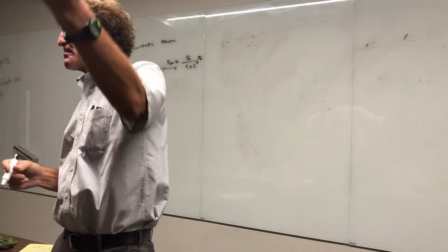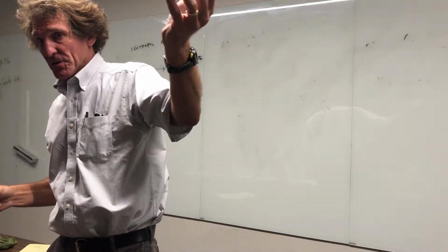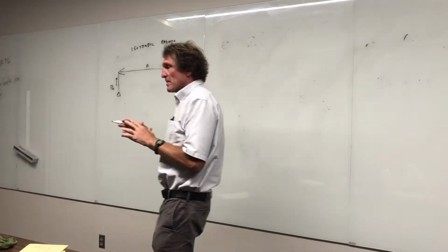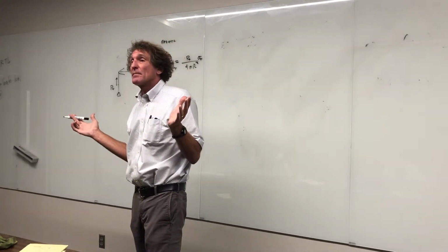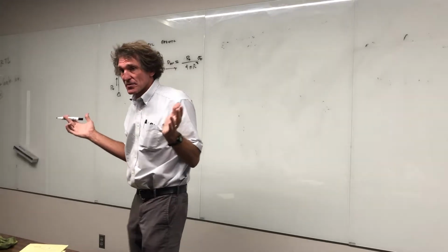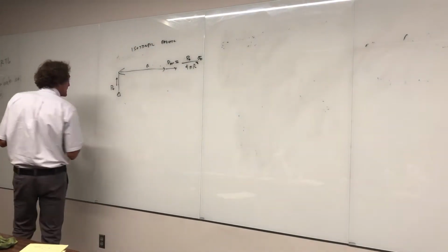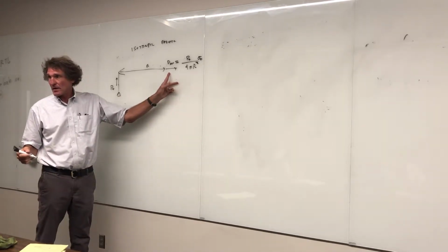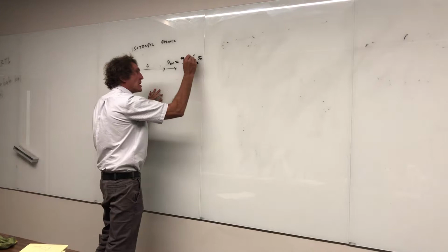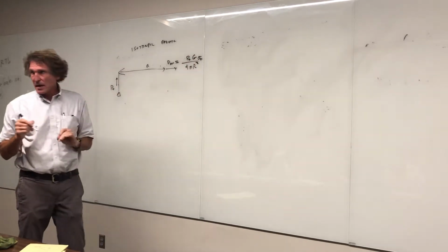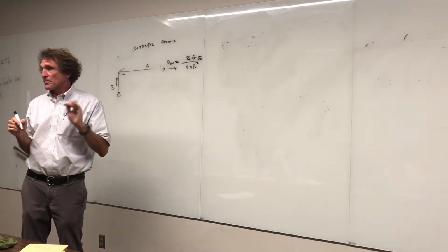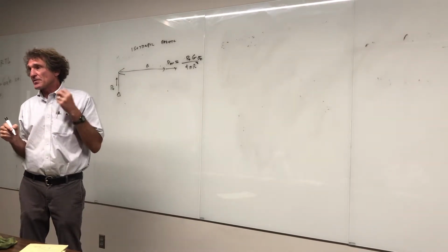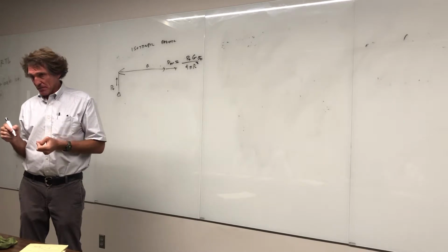As a matter of fact, a light bulb, to a large extent, could be thought of that too. Now, both of those I'm using only to give you an idea of what I mean by an isotropic radiator. It radiates the same in all directions. Now, antennas don't do that, but here's the way gain is used. We start by taking this equation. That's an isotropic radiator. Gain tells us how much better it is in a certain direction. And gain is a function of theta and phi. So as theta and phi change, the gain will change. Usually they talk about max gain of an antenna.